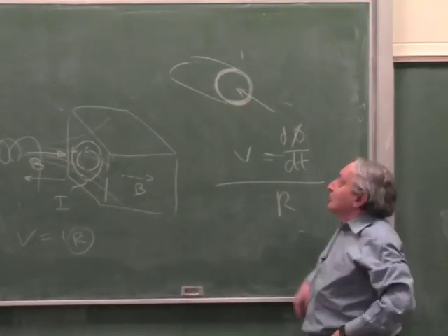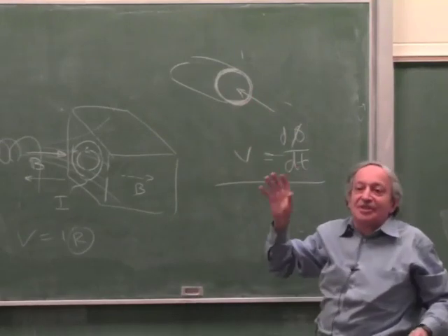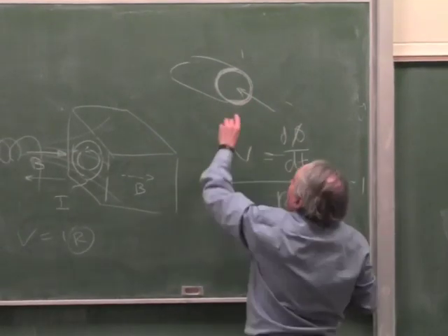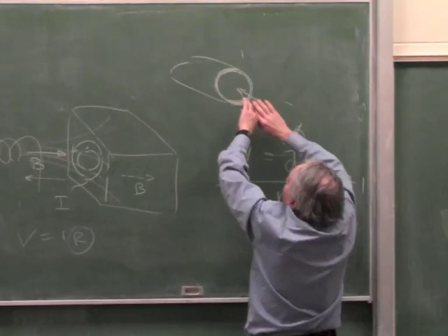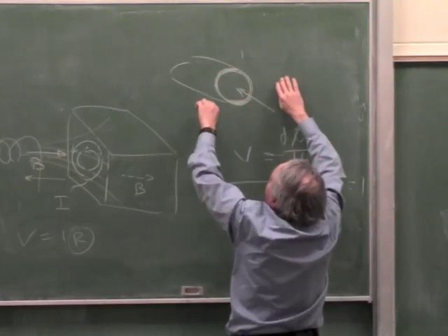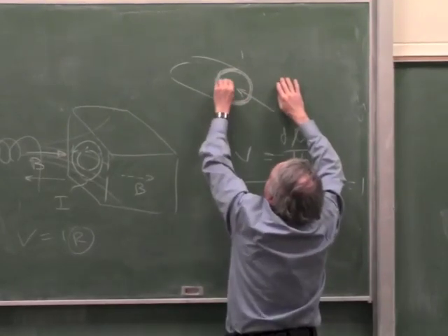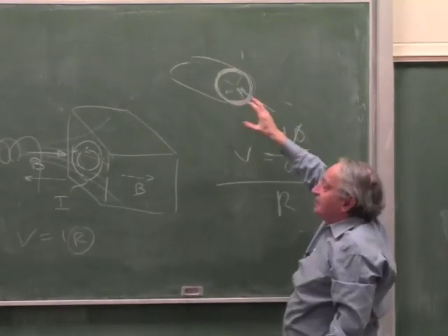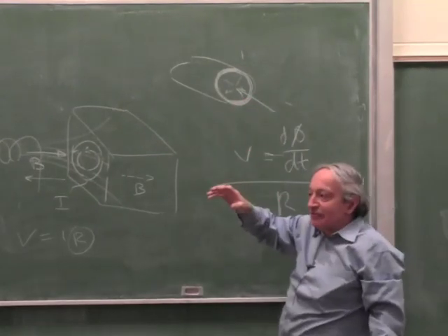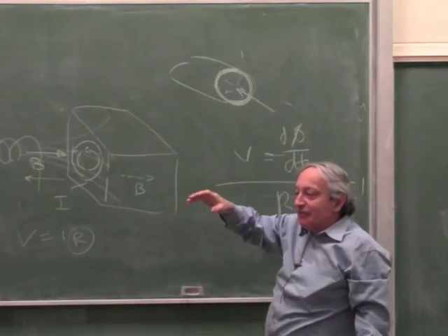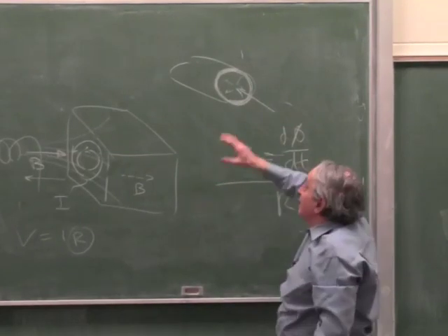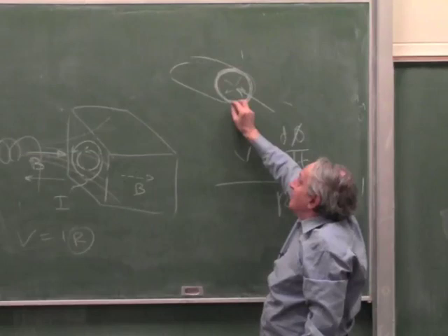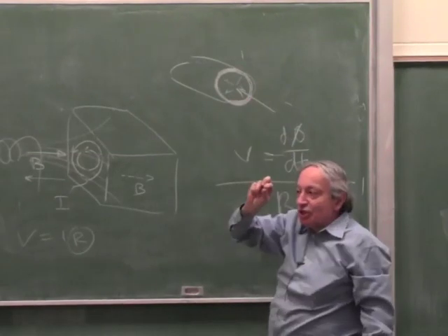So if the conductor was hollow or solid, it will be the same, because the current inside is repelled by itself to the outside. So basically all the current is repelled and it's only sitting on the skin. Now this effect gets stronger and stronger with high frequency, and at very high frequency the conductor is not good because the penetration of the current is very shallow.